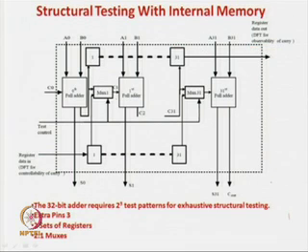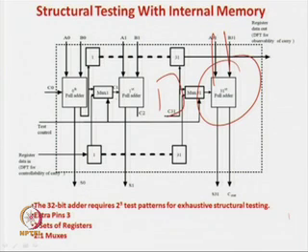Now, there is another point, that is about the observability. If you look at this full adder, these two are the inputs A and B, which can be directly controlled, but there is another full adder here which is directly feeding this carry. So, when you are going to test this full adder, we need to somehow decouple this, as in the last example of the AND gate we have seen. Then we can apply whatever test pattern is required.